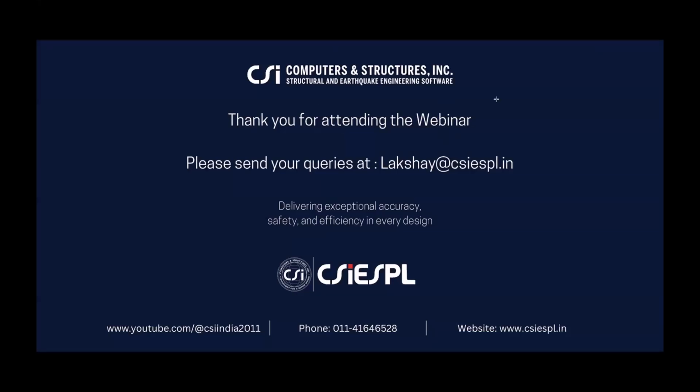Okay. Spectrum scaling is done with the spectrum cases in the base model, but I have removed them because there would be a lot of cases, which would be confusing if you have so long a list. Anyway, I'm not going to use them, so I kept only the scaled response spectrum. Scaling is done with the response spectrum case and the EQX auto lateral load case.